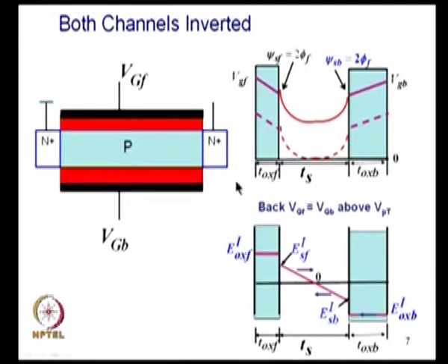The difference between the bulk MOSFET and this is, you can make it thinner and thinner, so that these two have more tighter control on the channel. If the thickness is small, if I have the drain here, if this is long compared to this thickness, the gate has a better control.